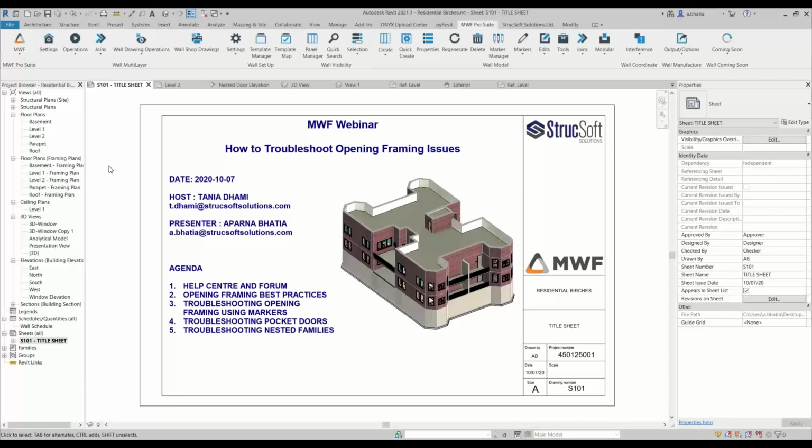And as I used to work in the structural discipline, it's always preferred to use the rough opening dimension so that we can actually place the framing around the door and the window the way it's supposed to go. It just gives you a lot more flexibility, and you don't have to mess with the architectural framing or architectural frame window type and so on. Does that answer your question? Yep, it did.